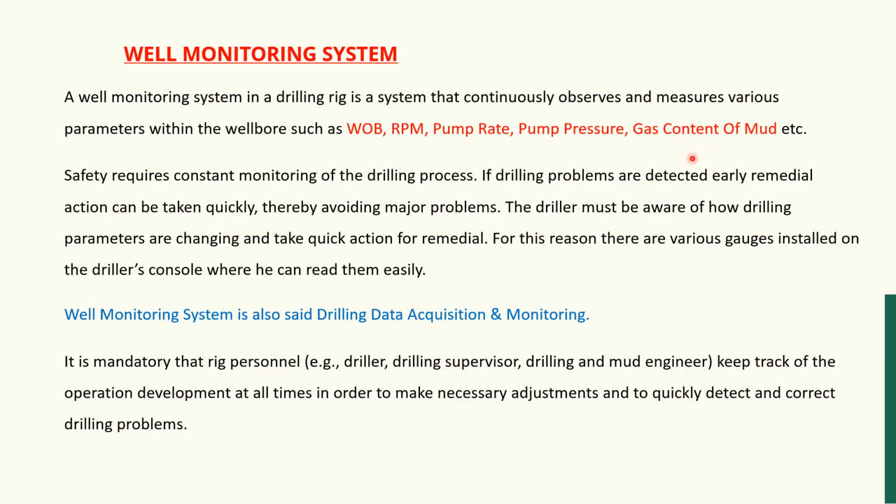So these are all very important, and to keep an eye on, observe, and measure all the parameters of the well is very important, because it gives real-time data. If the pressure increases, if the pressure decreases, if the volume of the mud in the tank increases or decreases without any genuine reason, it means it is giving some signal. On seeing this signal, the driller and the drilling supervisor take a positive step. They do the remedial action so that the drilling can be done in a safe manner.